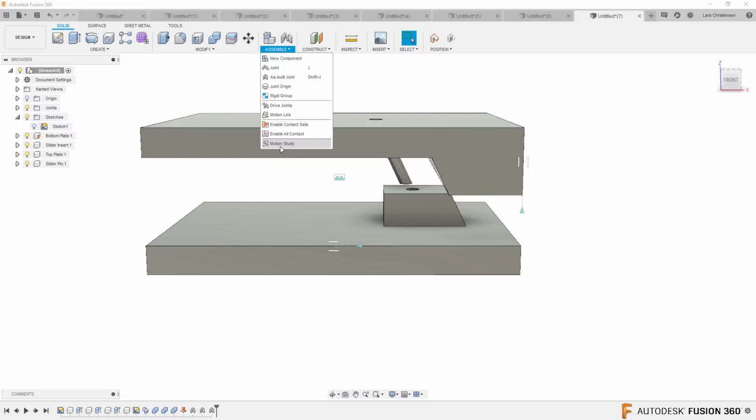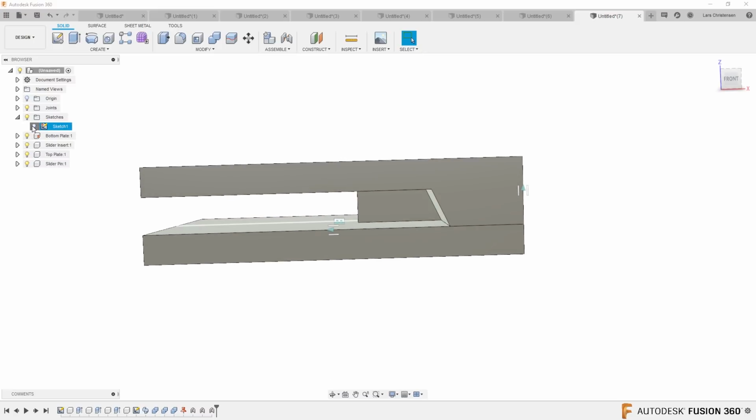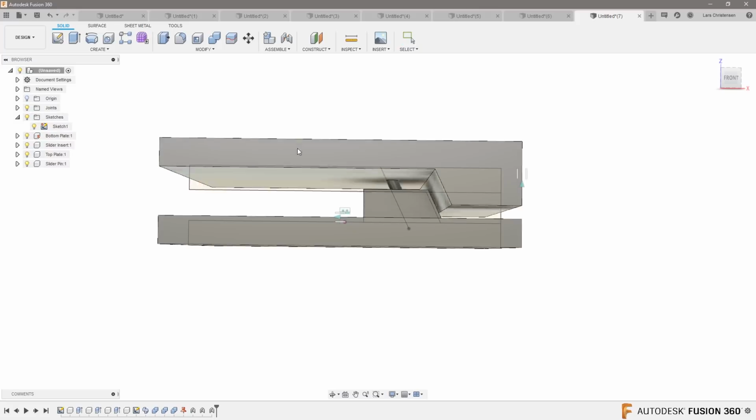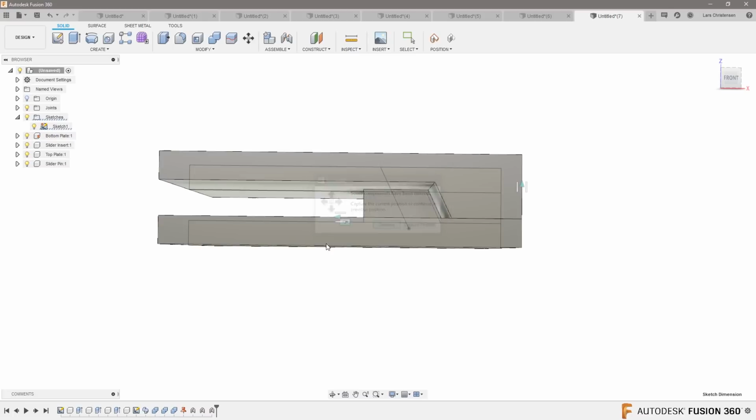And for that, I would probably just use a motion study. You could be tempted to use context sets, but that normally will slow things down. So model it up the way I did it here with the layout sketches to find out where everything should be. And then actually getting the live movements in here is more of, I call it, show.